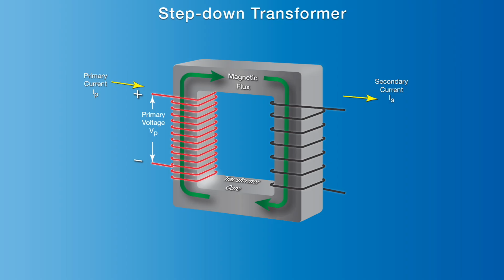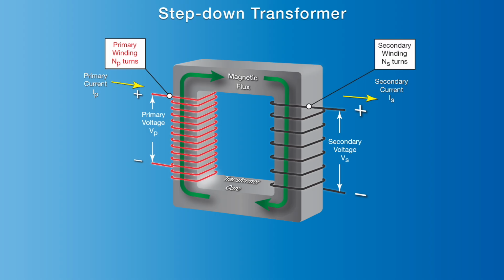Following a principle of electromagnetism, the magnetic field of the iron core will then induce an AC electric current to flow from minus to positive in the secondary coil's output, providing a step-down secondary voltage. The voltage step-down is dependent on the ratio of the primary coil windings and the secondary winding turns on the output coil. The bigger the drop in turns, the larger the drop in output voltage over input voltage.